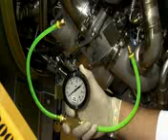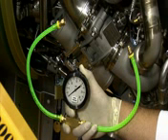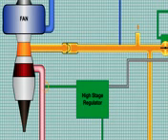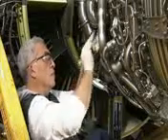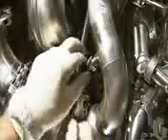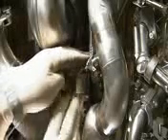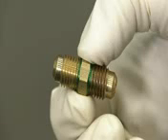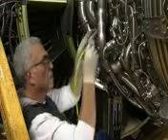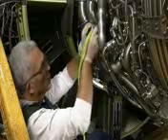To troubleshoot the high stage regulator, you will need the high stage test assembly. Recall that the supply pressure is taken from the high stage duct. Remove the supply line from the high stage duct, then, using this special fitting from the test kit, attach the supply line to the hose from the test supply assembly.